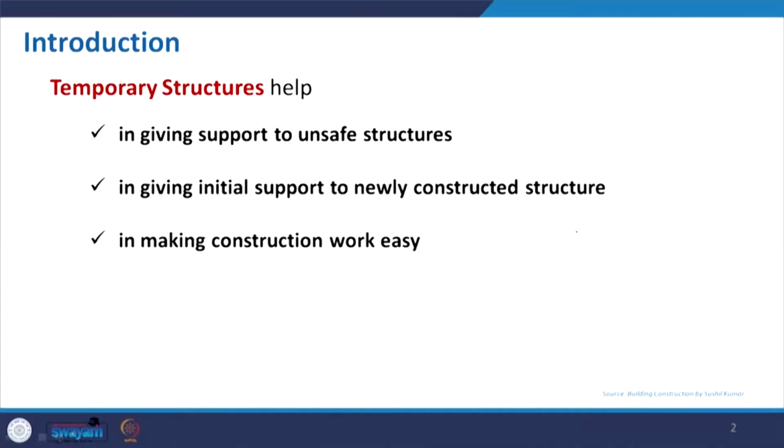In order to make those columns, slabs, etc., we also need to make some temporary construction, with material that can be wood, plywood, or steel, depending on the scale of the project and the available resources with the developer or the construction partner. That will help to support the newly constructed structural part, and also make construction work easy. This is something not really giving support to the structure, but giving you the framework.